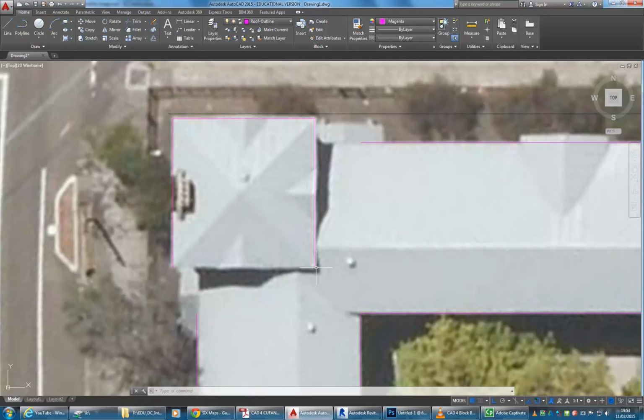Okay, so now again, I want the other side of that building to be copied down using hopefully a fairly round number. So looks close enough to 10,000 again, luckily. And it should be a square, this building. And that's really a good example of what I'm trying to show you, because if you were to just trace over this, even if you had it set to right angles, you might have it slightly off a square. And that'll just create work for you when you're working on it in Revit, because if everything isn't even, if you're copying things from one wall to another or rotating them and they're not exactly the same, you'll get things, you know, a fraction of a mil off, and it just creates work for everyone.